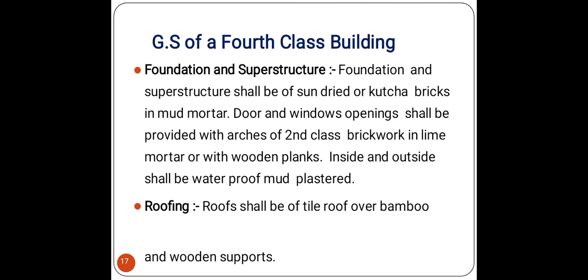Next, for the case of fourth class building, the foundation and superstructure shall be of sun-dried or kachka bricks in mud mortar. Door and windows openings shall be provided with arches of second class brickwork in lime mortar or with wooden planks. Inside and outside shall be waterproof mud plastered.